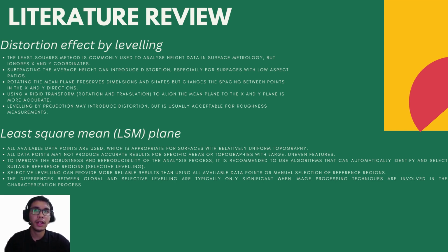Other studies suggest that when analyzing specific features, it can be helpful to use background regions, which are the areas surrounding the features of interest, as a reference to construct the least square mean plane. This allows for more targeted analysis of the features rather than using all the available data points. To improve the robustness and reproducibility of the analysis process, it is recommended to use algorithms that can automatically identify and select regions that are more suitable for use as a reference plane. This technique is called selective leveling. This can provide more reliable results than using all available data points or relying on manual selection of reference regions.